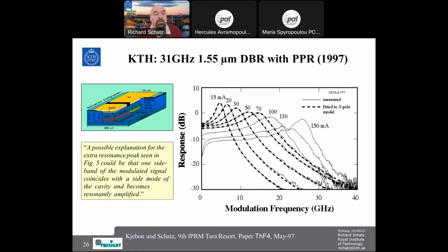For a pure EML, you just want a laser that has large power, and the bandwidth of the laser itself is not important. It's just the bandwidth of the modulator that is important. So, yeah, I hope I was clear, even if it was not the best pedagogical answer. You have no use of this if you're working with DMLs, but if you have intracavity modulators in your laser, you can utilize this effect.